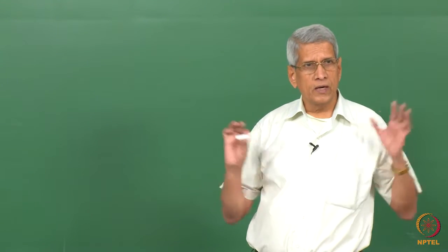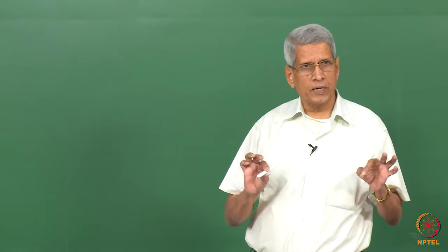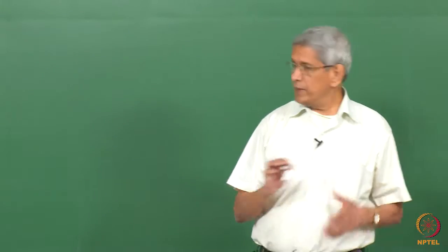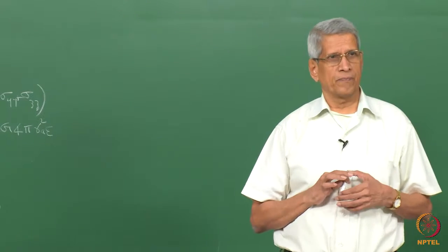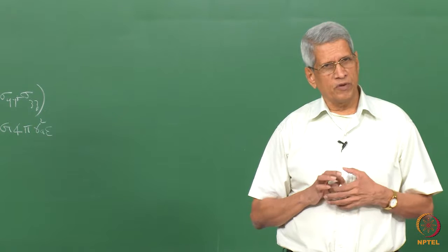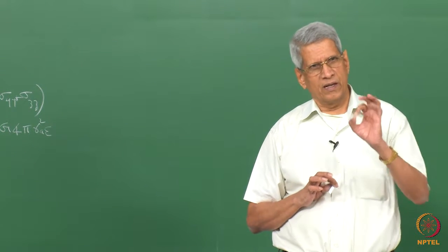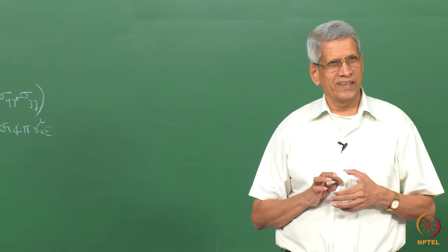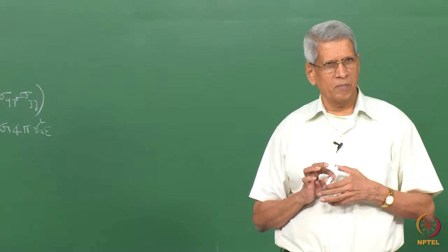Here what we have considered is only one aspect of the interaction energy. There are many aspects which we can consider. Suppose we assume that the point defect is there. What will be the modulus of the point defect? It's almost 0. What's the modulus of the dislocation? It's going to be high. Then there is the modulus of the matrix.